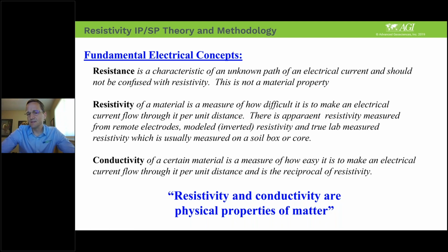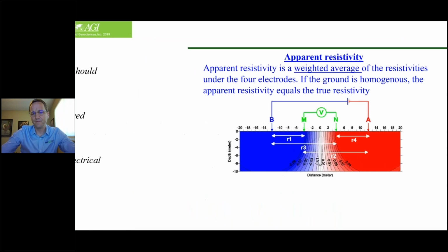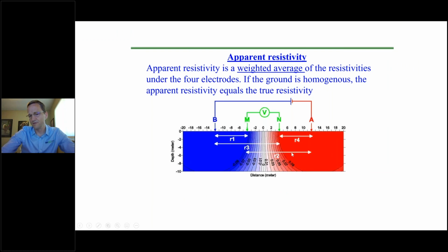In some cases, the operators will put the stakes at the required position, but they'll annotate the spacing wrong. And if you were to plot all the data and then you see one outlier, sometimes it's very safe to say that you can correct that spacing, the R1 or the R2 or the R3 or the R4, in post-processing if it all lines up.